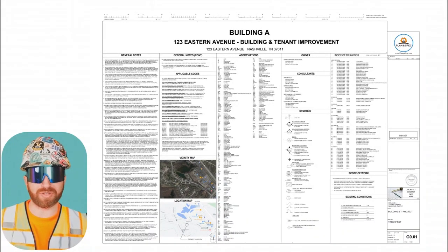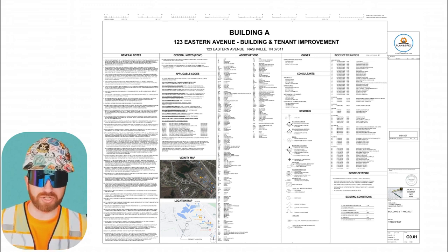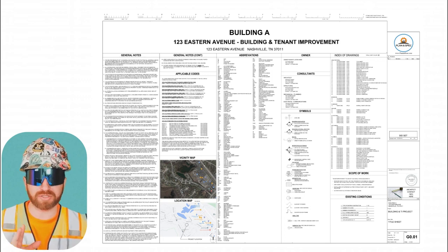No need to go any further in depth than that because most of these general sheets are pretty simple. Usually they're limited to one page, if not just a couple. The lessons learned in general is that when you're reading these drawings, skimming is a no-go. You have to read all the notes and you have to reread all the notes. There may be one small hidden note on any one page that, if ignored or missed, could cause a ton of headaches down the road.